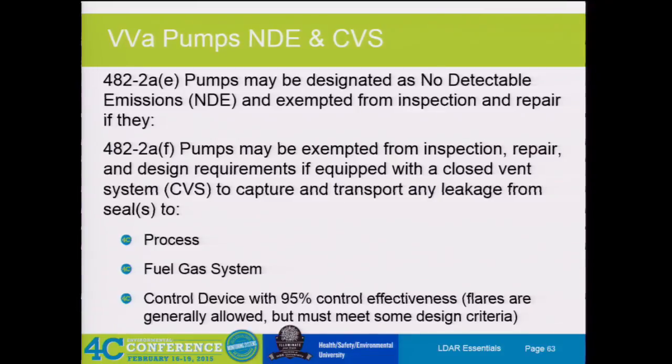Pumps may be designed as NDE, which is no detectable emissions, and they are exempt from inspection and repair if they're designed and equipped with a closed vent system that captures and transports any leakage from the seals to the process or fuel gas system or a control device, which would be your flare, which is 98 or 95% control efficient here.